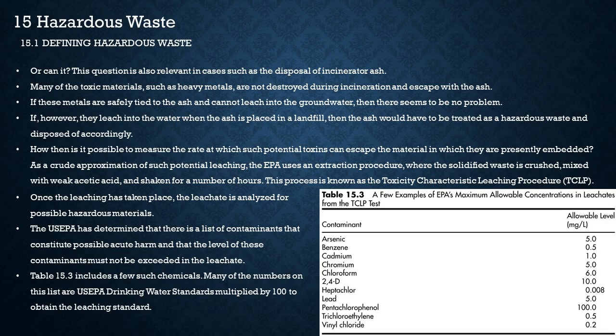This question is also relevant in cases such as the disposal of incinerator ash. Many of the toxic materials, such as heavy metals, are not destroyed during incineration and escape with the ash. If these metals are safely tied to the ash and cannot leach into the groundwater, then there seems to be no problem. If, however, they leach into the water when the ash is placed in a landfill, then the ash would have to be treated as a hazardous waste and disposed of accordingly.